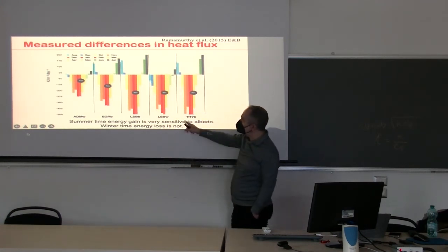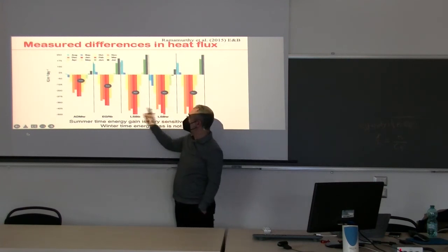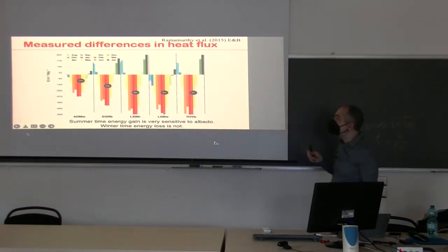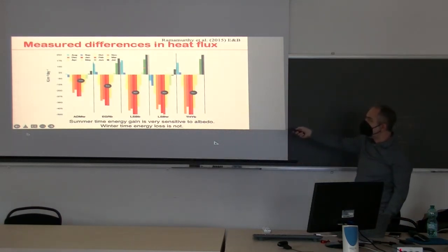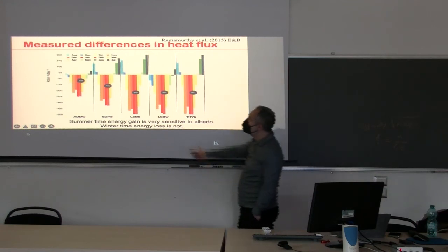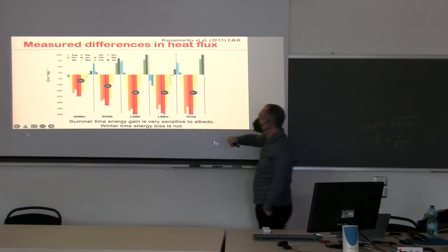But during the winter, the white one is losing more heat, as you expect, but the difference is really minor. It seems the winter difference in heat gain is much, much smaller. So the wintertime penalty of a white roof is really minor compared to the summertime benefits. That was kind of curious and interesting.